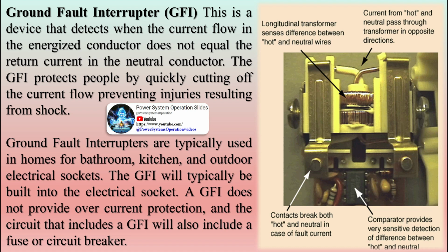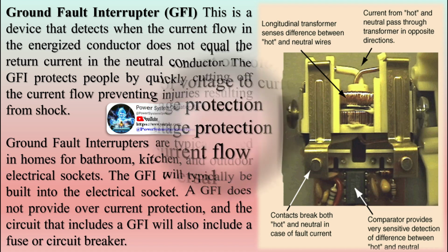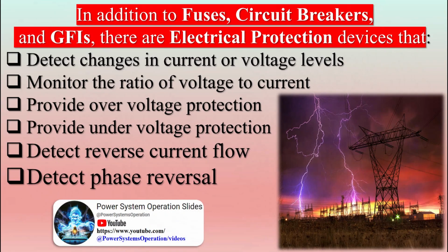Another question is, when is short-circuit analysis needed? The first short-circuit analysis should be performed when a power system is originally designed, though this should not be the only time. These studies need to occur with any facility expansion or with the addition of any new electrical equipment such as circuit breakers or new transformers and cables. Without any new additions or changes, short-circuit studies still need to occur on a regular basis of at least every 5 to 6 years.